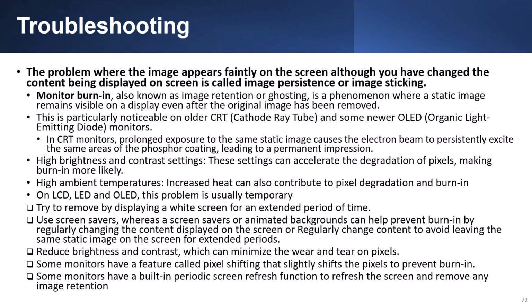In CRT monitors, prolonged exposure to the same static image causes the electron beam to persistently excite the same area of the phosphor coating, leading to a permanent impression. High brightness and contrast settings can accelerate the degradation of pixels, making burn-in more likely. High ambient temperatures will increase heat that can also contribute to pixel degradation and burn-in. On LCD, LED, and OLEDs, this problem is usually temporary.